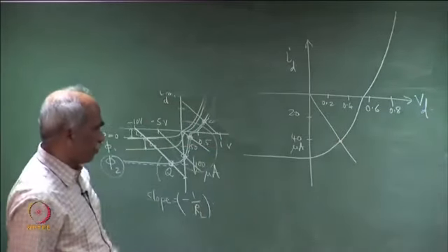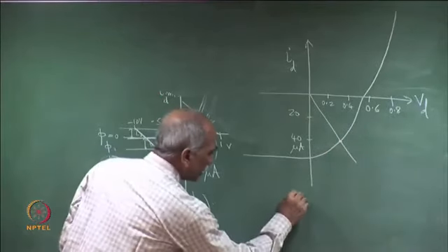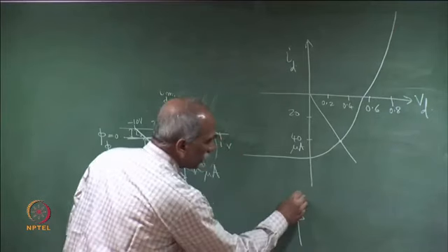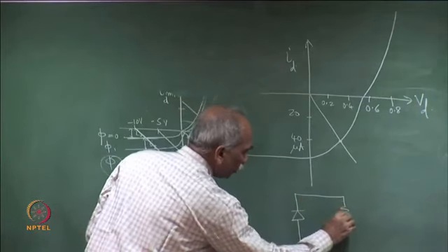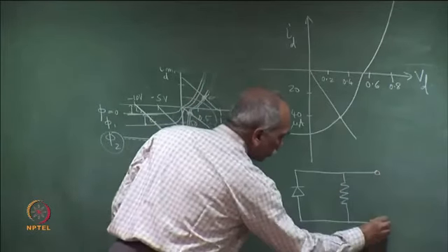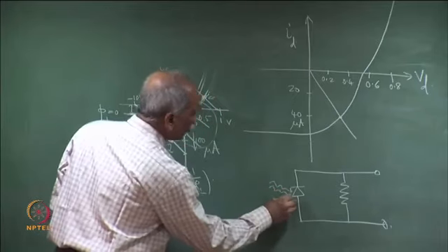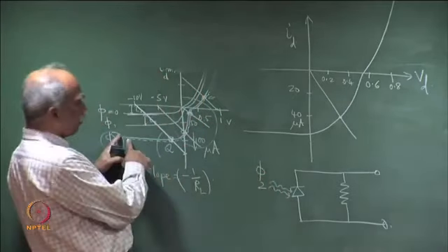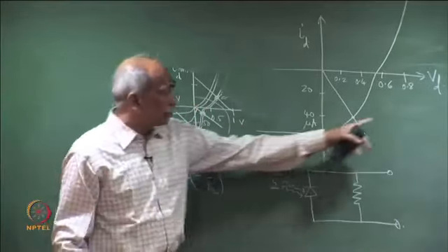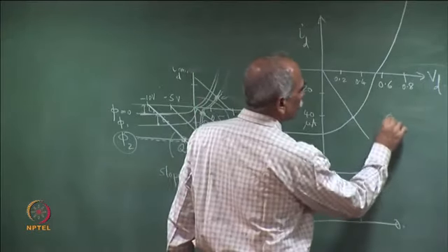So, what does this mean? We are looking at a photodetector, a photodiode here, and a load resistance across it here, and incident photon flux phi 2. The same curve, I have expanded this part of the curve. We are in the fourth quadrant. So, this is the region of operation of a solar cell.